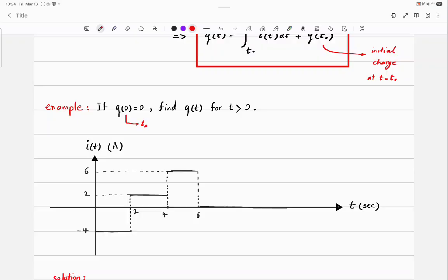How about voltage source? Voltage source has different symbols. I mean, pick any one. What does it mean if I write 4 volts besides that circle? It means that no matter what the rest of the circuit is doing, what kind of current or voltage is applied to the rest of the circuit, the voltage across these 2 points, or the potential difference between these 2 points, is always 4 volts, meaning that the positive terminal is always 4 volts higher than the negative terminal.